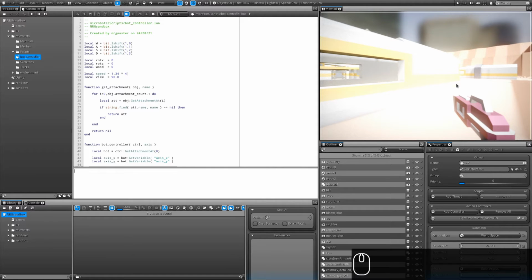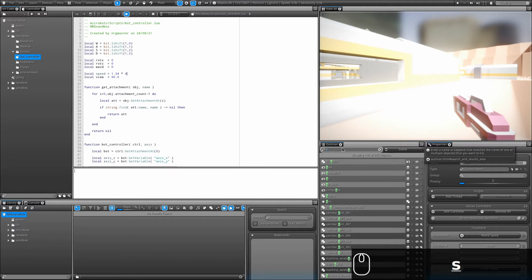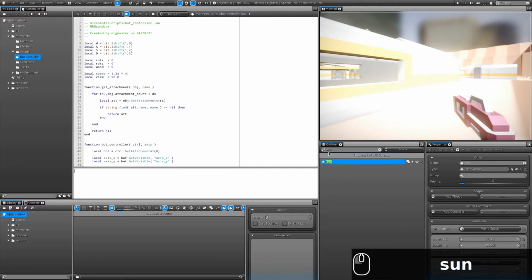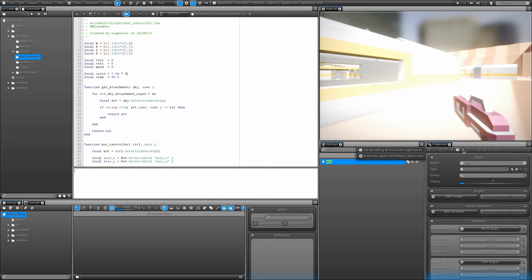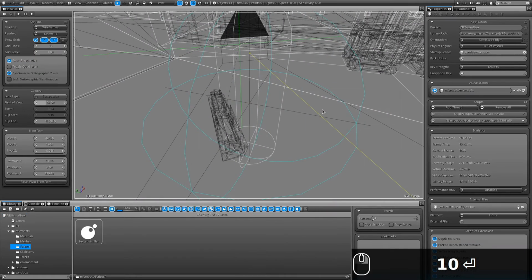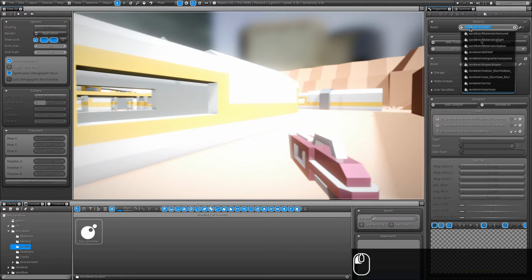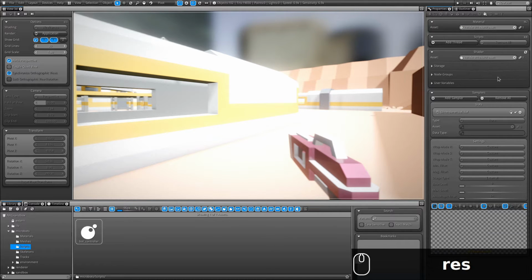The first thing that I'm going to do is tune down the sun intensity. So under the outliner, I'm going to pull my sun object up, and I'm going to go under light source properties, and first cool it down to 10. Next I am going to head over to my default layout to have a better view of my final output. I'm going to go under properties and material, and open up my result material,